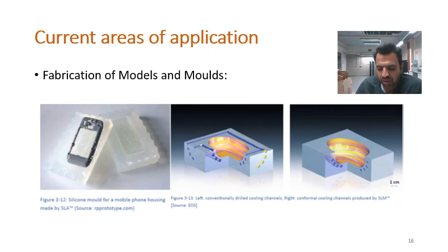The advancements in 3D printing or additive manufacturing of metals has now made it possible to manufacture the metal mold itself. The advantage of using additive manufacturing technology is that you can create conformal cooling channels into the molds, which help to achieve high cooling rates and also increase the life of molds.